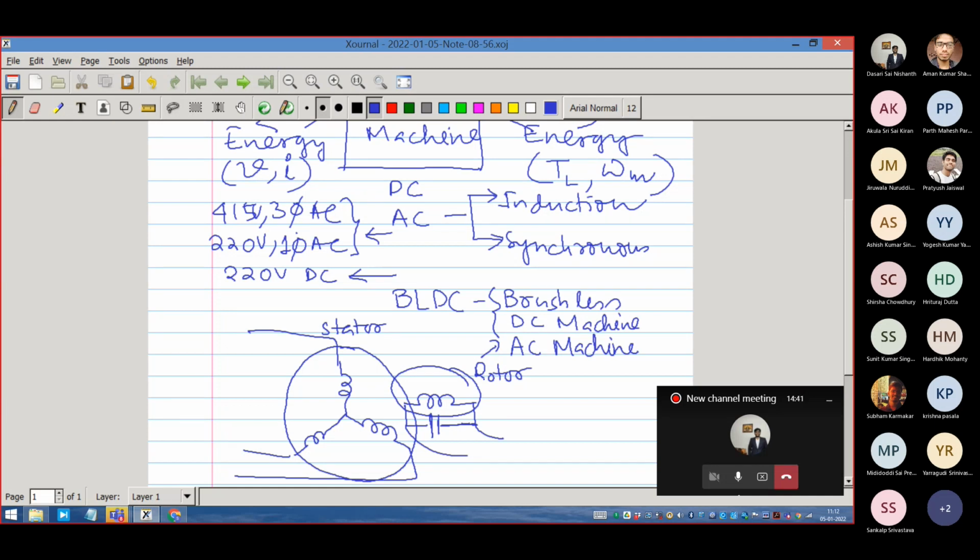Still made of iron core, maybe cold rolled grain oriented variety, that means magnetic material. Whereas in the recent machines, in order to improve efficiency and reduce many kinds of complications, only connection complications, no theoretical complications, sometimes the rotor is nowadays going into permanent magnet material.